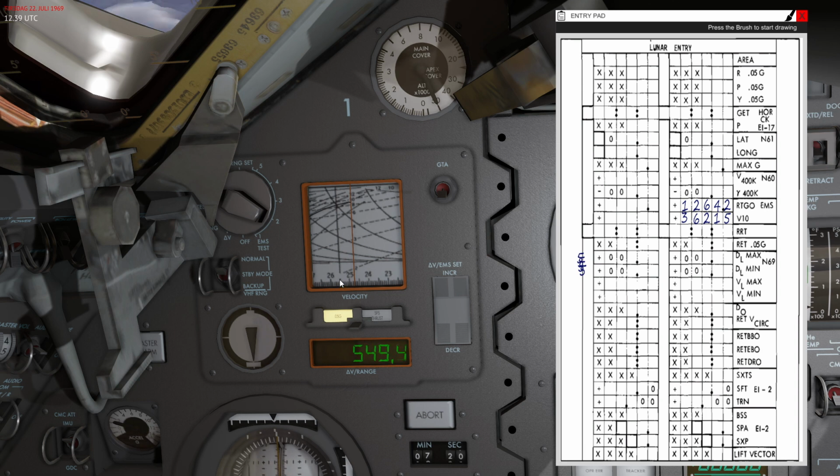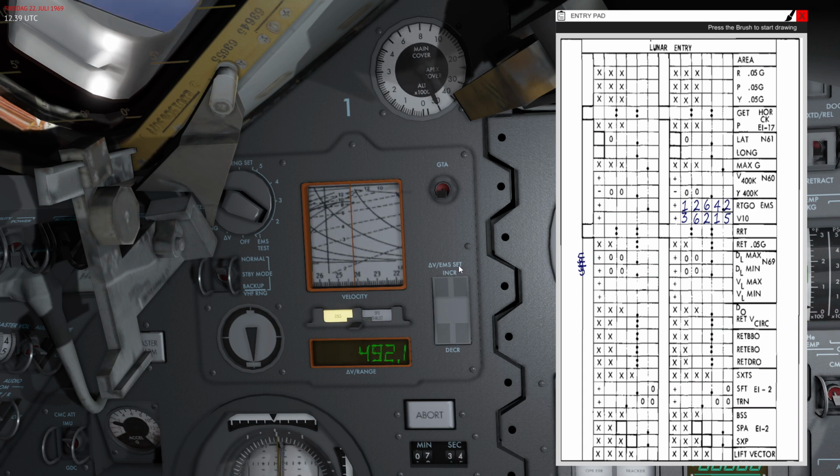25,500 feet per second is basically what it requires the capsule to have to be in a circular orbit. So if you skip out of the atmosphere too fast and too early with a lot of upwards velocity, you will actually skip out on an elliptical orbit that will take you far away from Earth.